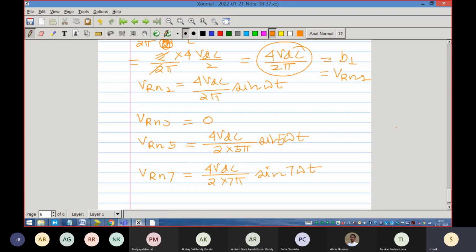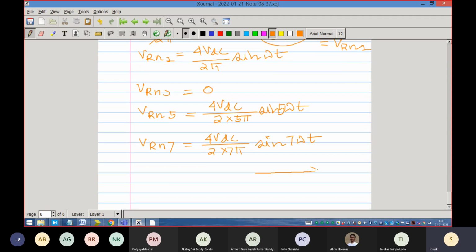So with this we just see that the phase sequence changes. We have to see in the next class how the phase sequence change produces a different kind of torque pulsations. The normal torque production happens between the flux and the current. So normal torque production, we'll see that the flux level of the machine, wherever it is, and the current MMF of this machine, wherever it is, their angle between these two things, I have drawn a little wrongly, their angle will not be like that. The angle is somewhat like this.